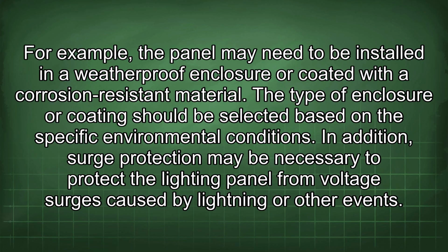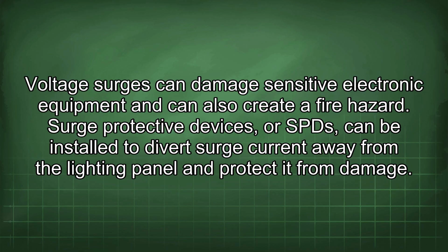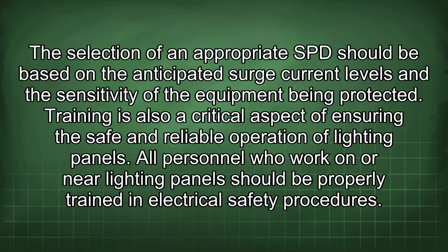In addition, surge protection may be necessary to protect the lighting panel from voltage surges caused by lightning or other events. Voltage surges can damage sensitive electronic equipment and can also create a fire hazard. Surge protective devices, or SPDs, can be installed to divert surge current away from the lighting panel and protect it from damage. The selection of an appropriate SPD should be based on the anticipated surge current levels and the sensitivity of the equipment being protected.